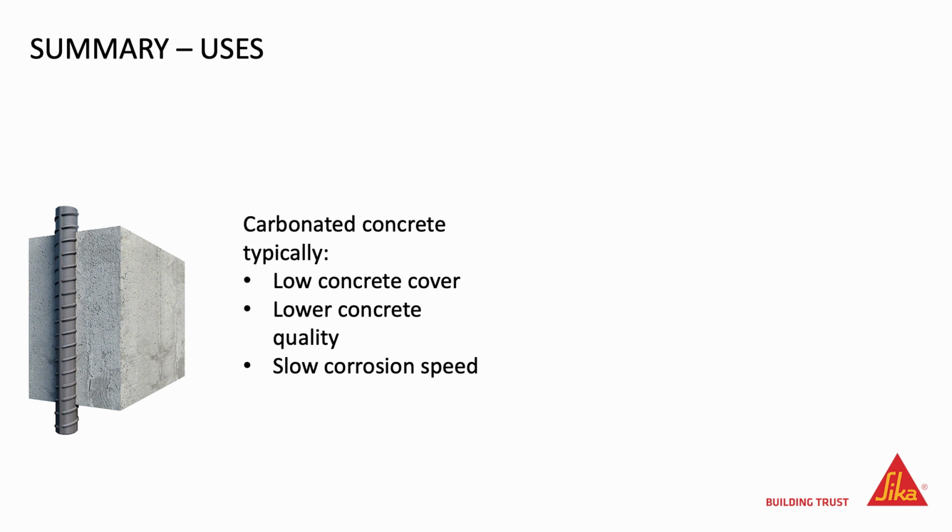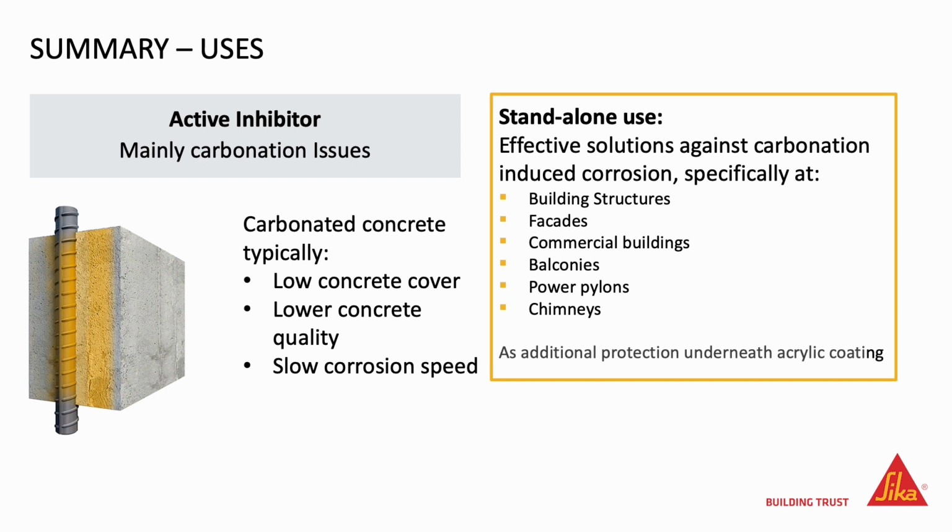In summary, typically for carbonation-induced corrosion, we find low concrete cover, relatively low concrete quality, and slow corrosion speed. For all of these factors, due to the necessity to reach the reinforcing bars level, active inhibitors are very effective to deal with carbonation-induced corrosion. They can be used alone or as additional protection underneath acrylic protective coatings.